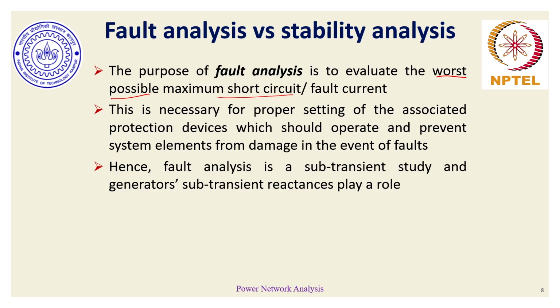But we never went inside the synchronous generator. We never made use of the synchronous machine reactance in steady state. Most of the studies you would encounter in power network analysis rarely involve the application of Xd or Xs in the steady state period. Only the value of Xd double dash, which is the subtransient reactance, finds its application in fault analysis, because using Xd double dash only we will be able to find the maximum possible short circuit currents.